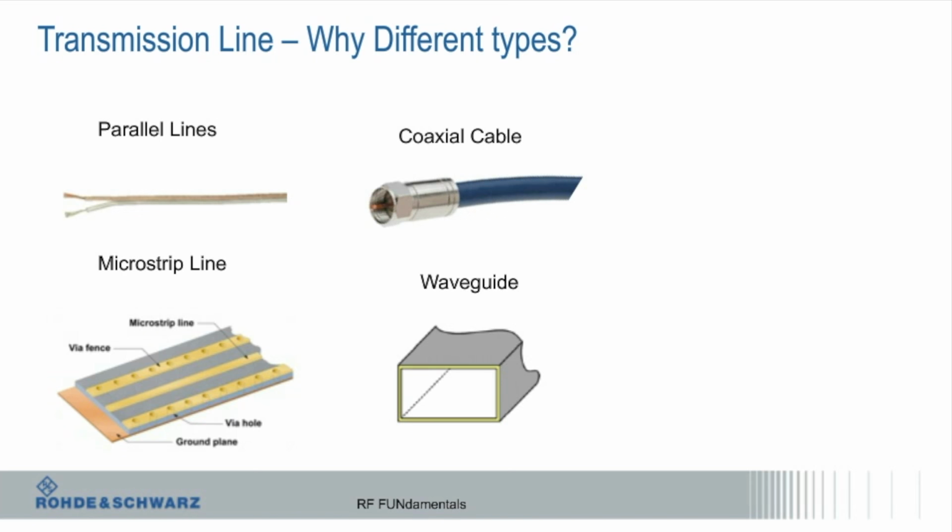But interestingly, I had a customer I was doing interference hunting for, and the customer was AT&T. We were out looking for somebody interfering with their base station, and it was actually an FM station going onto the cell phone network. The guy I went out with and I went into a radio rack for an FM station, and they had just big copper pipes, because they do really high power. You can buy copper pipe that's the right dimensions to make a waveguide. That was kind of interesting to me.